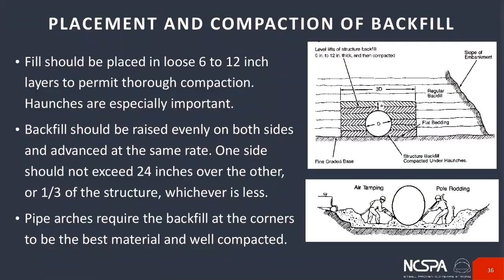So, placement and compaction of backfill. Like I mentioned a minute ago, the material under the haunches has to be in firm contact with the entire bottom surface of the structure. The haunches are the most difficult to backfill and compact, and sometimes don't receive adequate attention during the process. So care must be taken to eliminate voids and soft spots in those places.